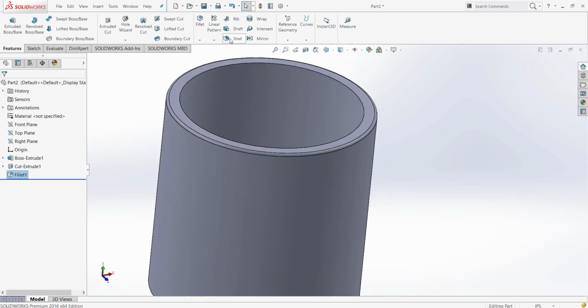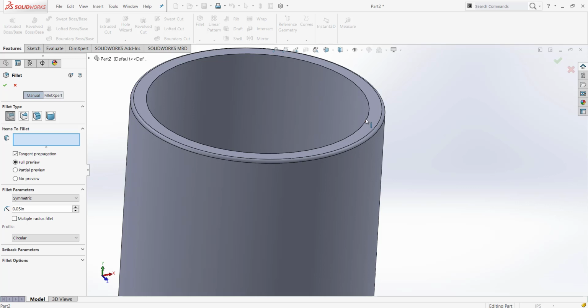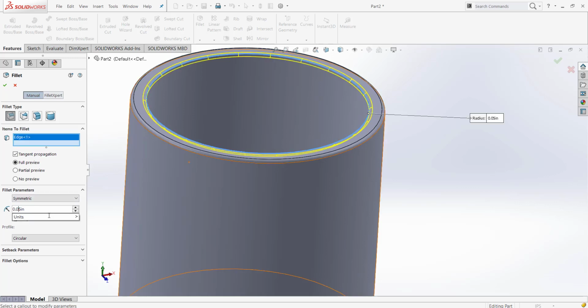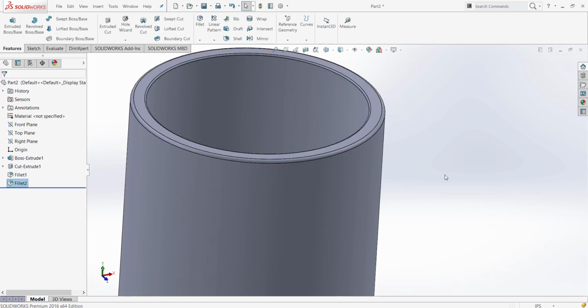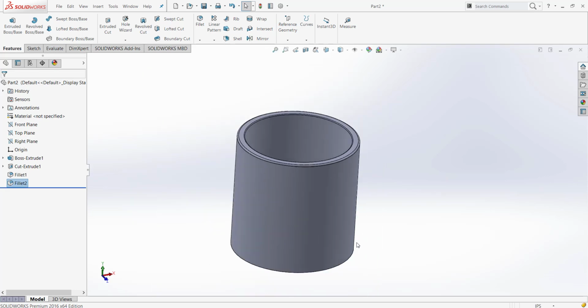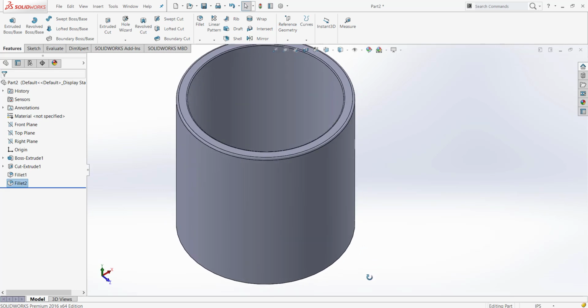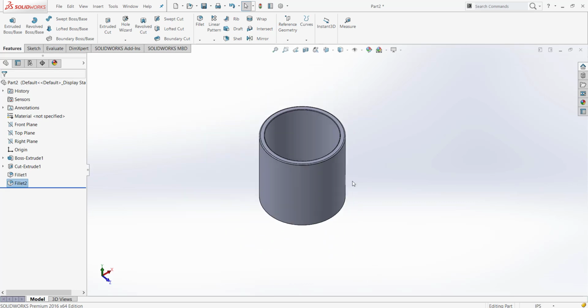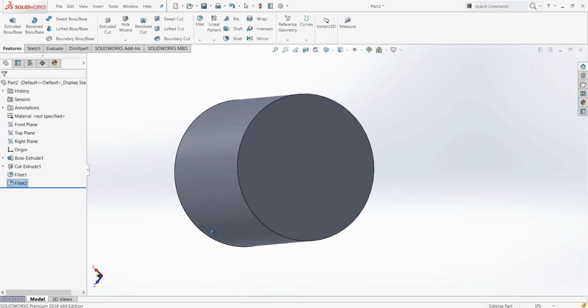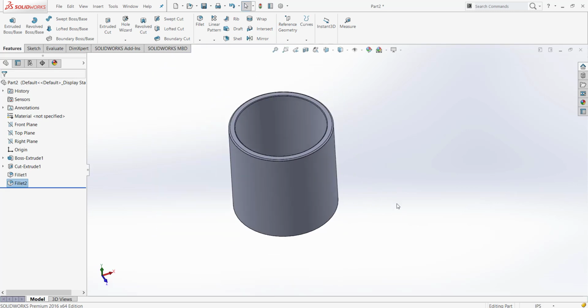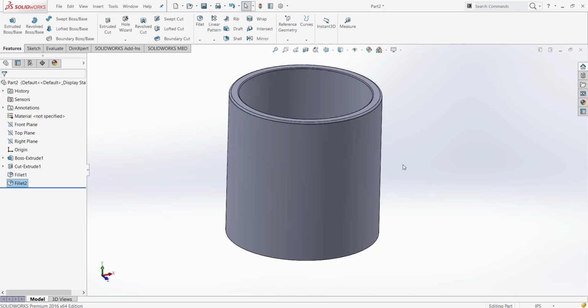And maybe the inside I also want a fillet, but perhaps the inside can be a little smaller than 0.05, perhaps 0.025, given that you don't directly place your mouth. So these are things you have to consider when designing, so that as you're designing, you're taking into account everything that your part will go through, from manufacturing, how easily manufacturable will this be, the volume that this can produce, its reliability when it goes out in the field. What's this for? Is this for hot liquids or is it for cold liquids? So have you picked the right material for it?